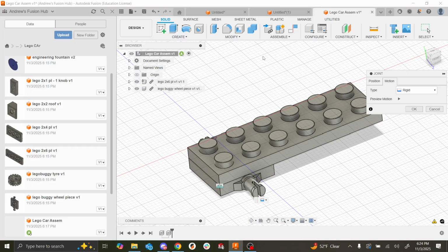So keep that in mind. I'm not really going to be going over that today because that's a little bit more advanced, but if you want to create stuff like belts and pulleys and gears that mesh with each other in the assembly, then keep in mind that you might have to use the joint tool instead of the constraint function.